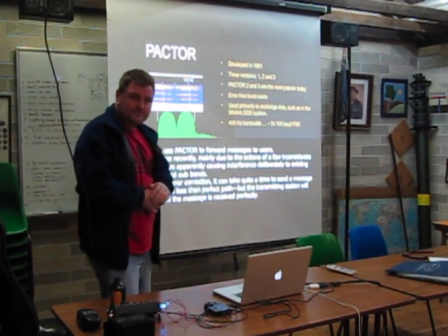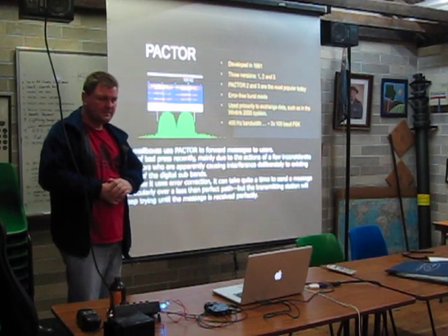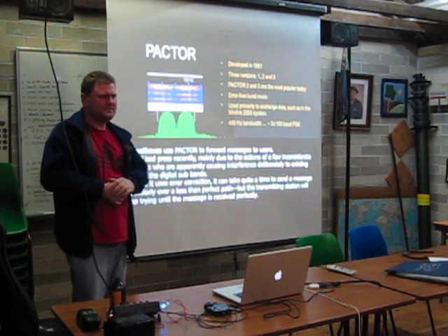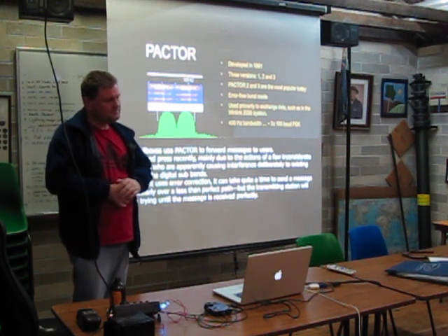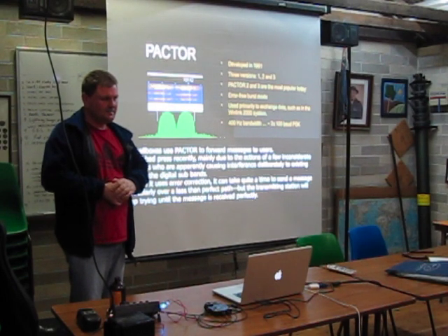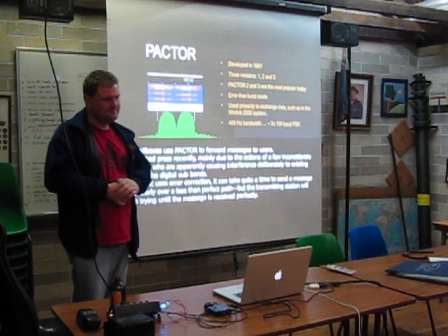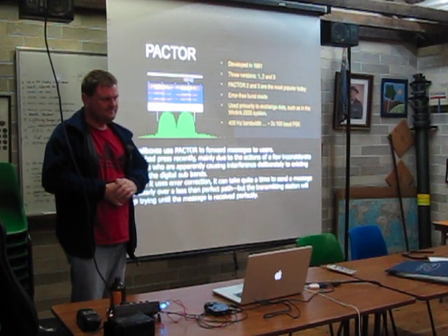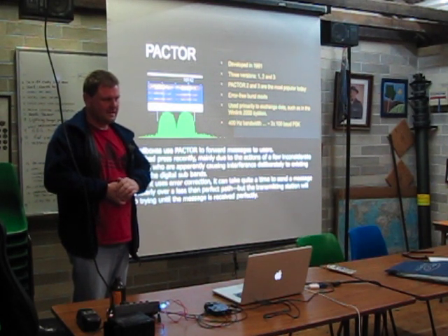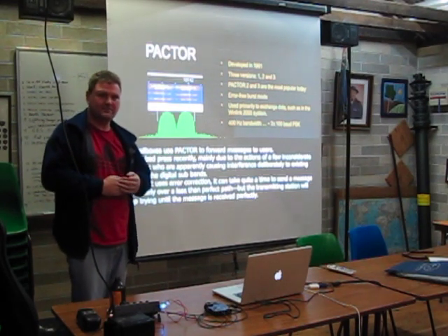Is the reason why you actually have to buy that hardware device that it's a proprietary chip? Proprietary, yes. The encoding is proprietary. Pactor 1 is actually in the public domain. But you still have to have a box because computers are not good enough on timing. So you have to have a dedicated box to do the timing: send, receive, send, receive. But for the others, that's all box. Yeah, the latency requirements and everything are quite stringent, so it's not practical to do it with a sound card.